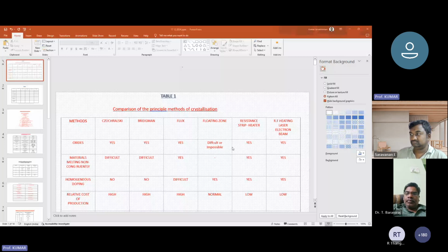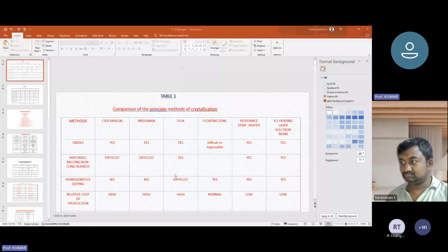It is double-sided, I'm sorry. The thickness is roughly about 350 or so, and then the thickness variation is less than 10 micron. You also measure the bow, which is less than 25 micron. And it is etched in order to understand the defect density, or if there are subsurface damages. Polishing is also done down to this thickness. And then subsequently, the wafer is used for the epitaxial process or for any other device fabrication.